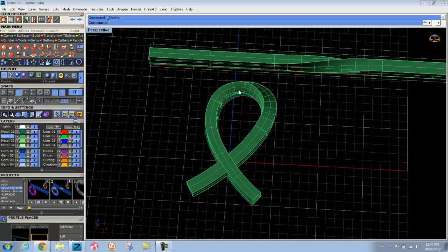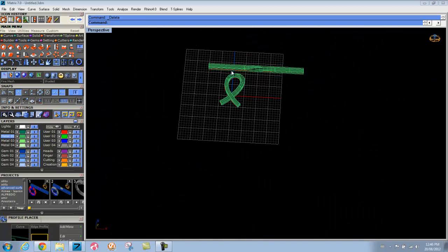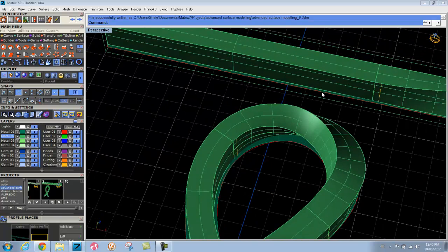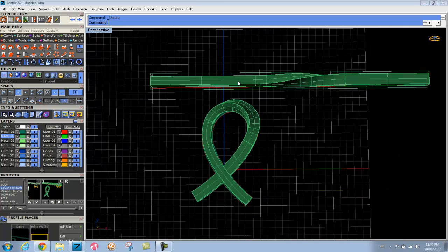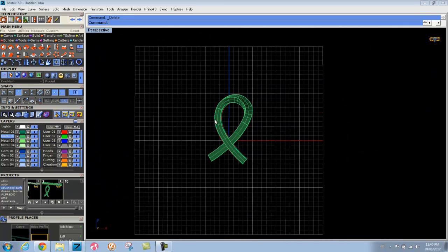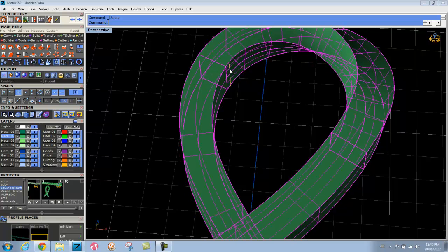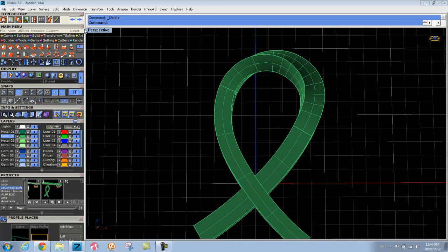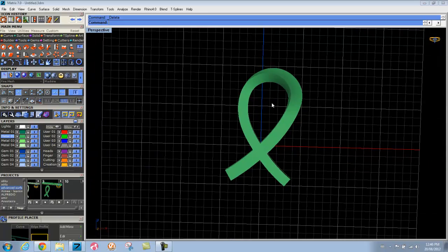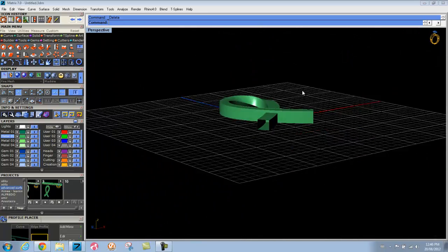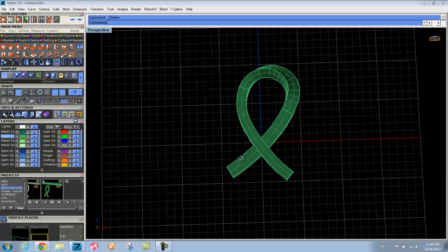And if we're finished with this flat object, you might want to save that, just in case you need to go back there at all. But when you're finished, you can delete that flat surface, and then that connection is broken. And then there's your object. So it's at least a very good way of quickly mocking up this shape.